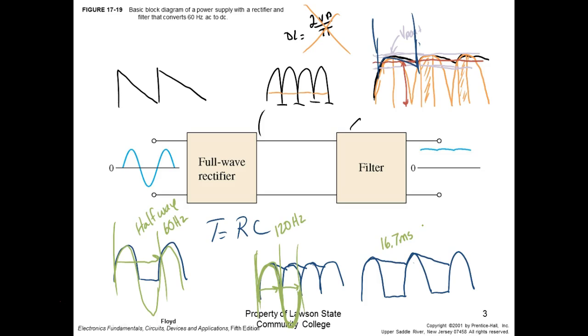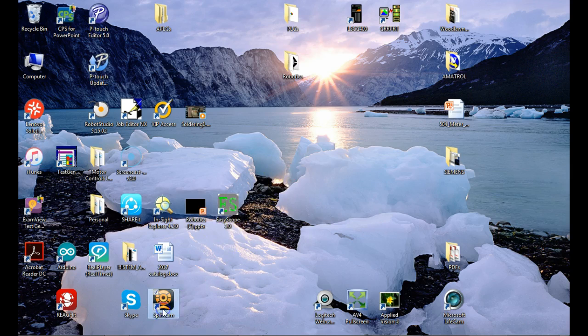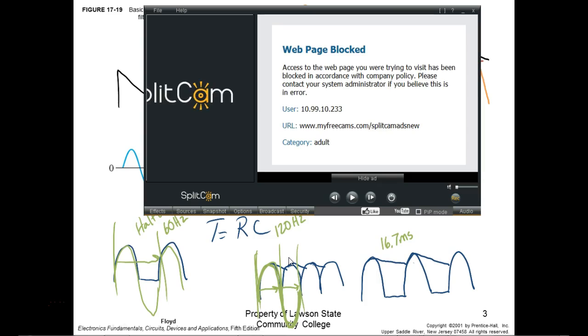A perfect example is this function generator right here. So this function generator, how can I change the frequency? Alabama Power gives me 60 hertz. So how can I come up on this function generator and set whatever frequency I want, as long as I'm in the ranges? Electronically, right? We come in, we rectify it, generate a negative and positive DC voltage, and then we control the negative and positive DC voltage, and now I can generate AC at another frequency.